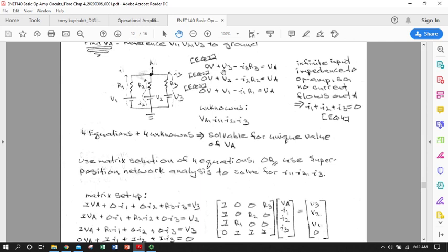And one of them is sort of a brute force method, which would get you there regardless, and is very amenable to very, very large complex circuits, and that's a matrix method. It relies directly on KVLing each branch and then KCLing the node point. So I'm going to apply Kirchhoff's voltage law to each of these branches